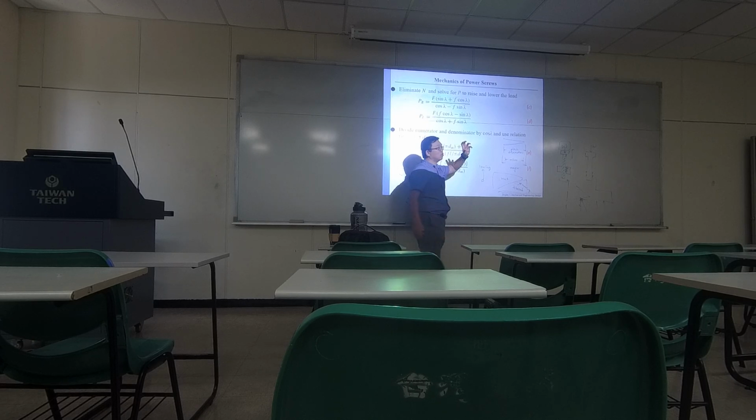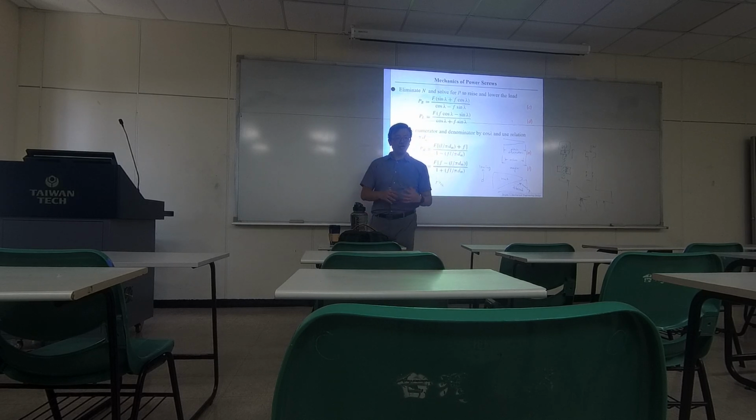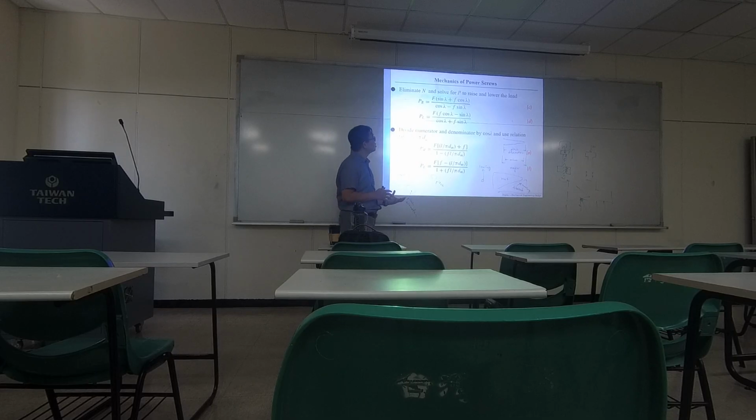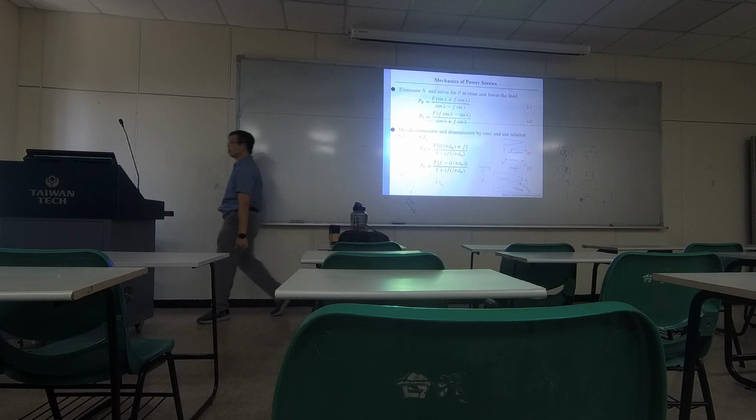So what's affecting the required force? How much weight you are pushing up? What's the incline angle of your thread? How much friction force you have between the thread and nut? That defines how much force is required to push the object up or to push the object down. That's the result of the force balance.